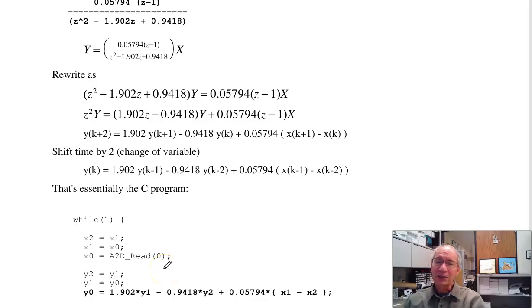But to do that, I need to go from the S-plane to the Z-plane. That's actually not too bad either. Just do a mapping. If I have n poles in the S-plane, I have n poles in the Z-plane, everything maps as e to the sT. And that's homework set number 11 for ECE 376.